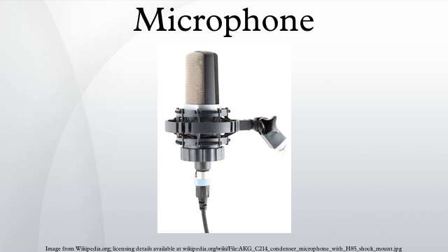The capacitance of the plates is inversely proportional to the distance between them for a parallel plate capacitor. The assembly of fixed and movable plates is called an element, or capsule. A nearly constant charge is maintained on the capacitor. As the capacitance changes, the charge across the capacitor does change very slightly, but at audible frequencies it is sensibly constant. The capacitance of the capsule and the value of the bias resistor form a filter that is high pass for the audio signal, and low pass for the bias voltage.